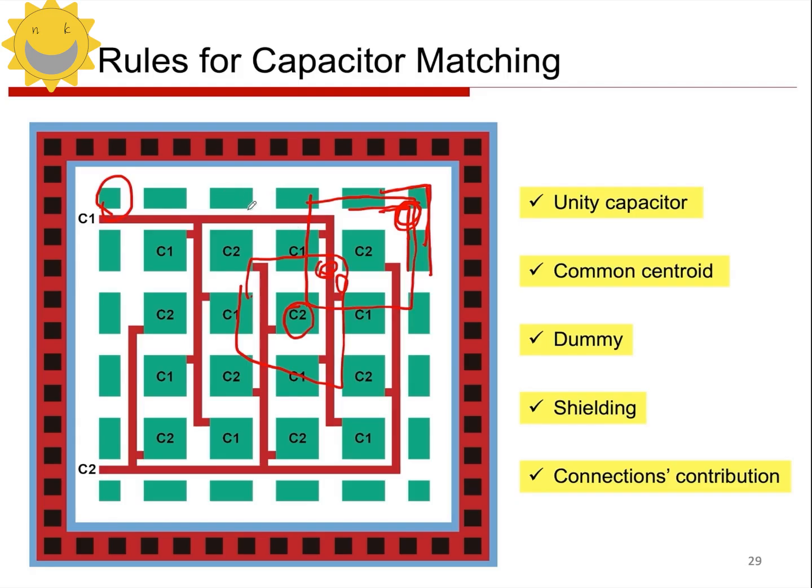For example, these are all capacitors. After I put these capacitors here, I will not leave the capacitors above and below unconnected. Leaving them floating here is not acceptable. They must be connected. Moreover, since they don't serve any functional purpose in the circuit, these devices must be shorted out. They definitely need to be shorted. So it's important to note that matching devices must be shorted out.